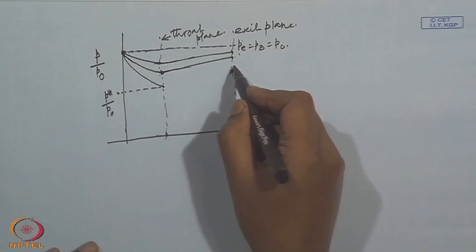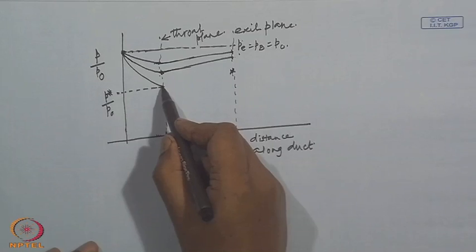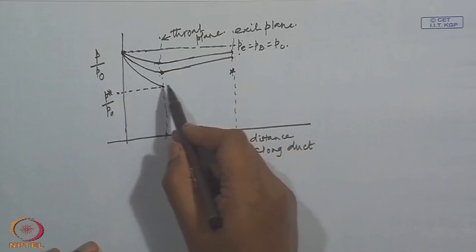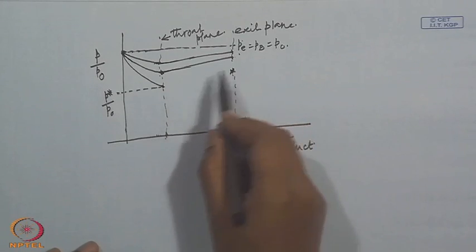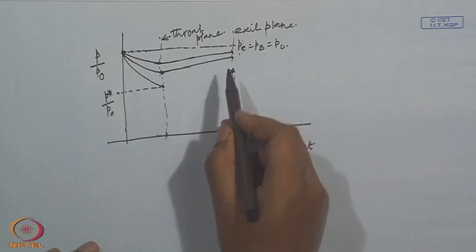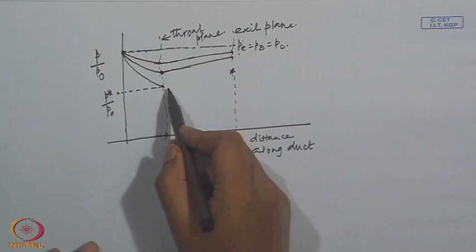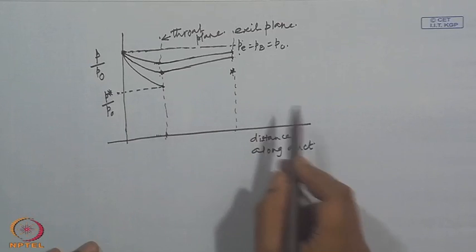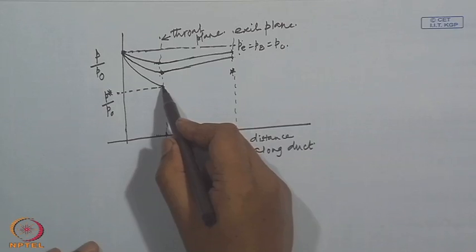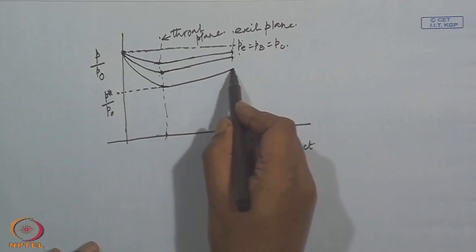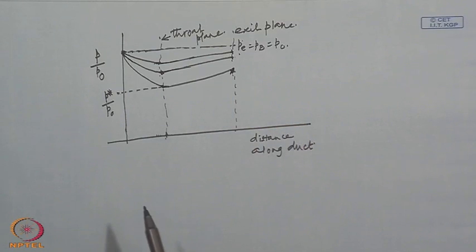For this particular value of the pressure, we have reached the sonic pressure at the throat, and flow velocity at the throat also becomes sonic. However, the pressure at the back is not yet sufficiently low to cause further expansion in the diverging part. Consequently, the flow in the diverging duct will again decelerate and will reach this value P b.